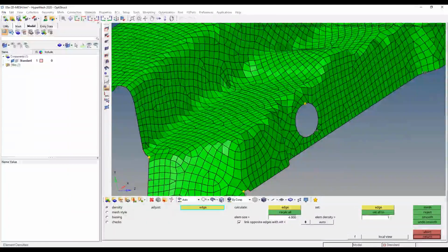They sort of serve as a guide there. We just want to be smart about turning off some of the edges when we have too many in place. And you also see, Garrett, that for the same thing, the mesh quality is really poor. You have Jacobian issues, you have warpage issues, so it's too free form. And as you said, you need those edges to define more accurately the geometry you have.